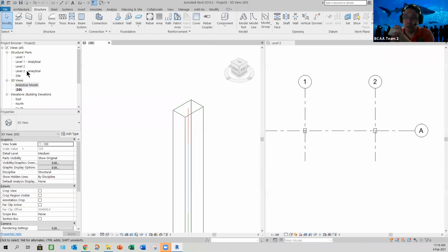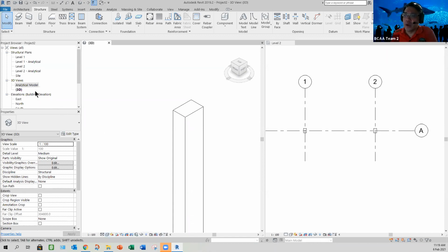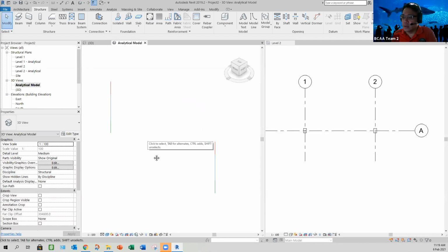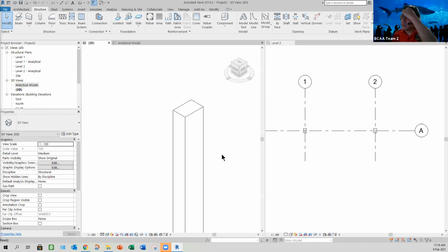If you're doing just the model, like in 3D view like this, you don't need this, and this should be wireframe, hidden line. If you are doing analytical model, you see like this is correct. The height model, you only see the thin line. Okay, questions?